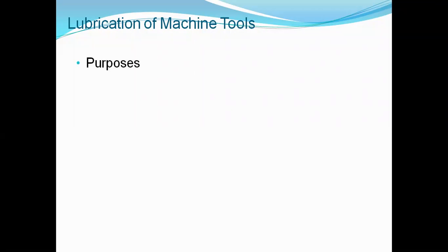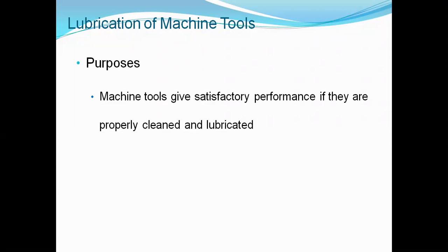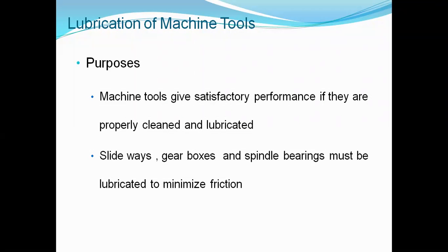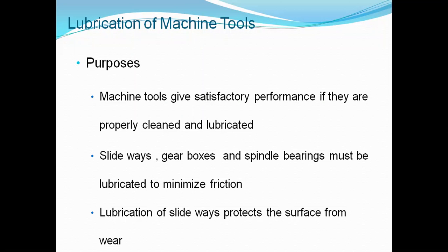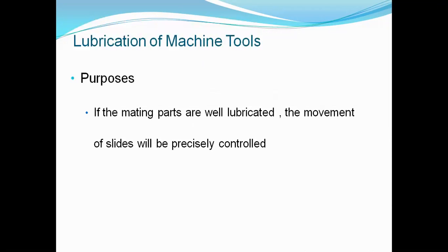Now, lubrication of machine tools, purposes. Machine tools give satisfactory performance if they are properly cleaned and lubricated. Slideways, gearboxes, and spindle bearings must be lubricated to minimize friction, as we have observed in lathe and shaping machines. Lubrication of slideways protects the surface from wear.